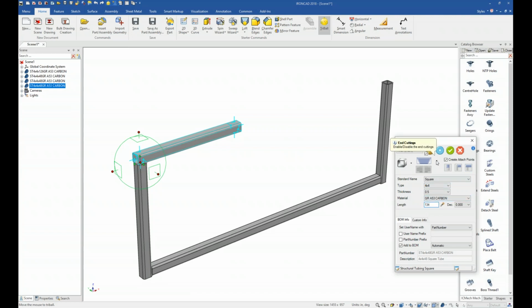And we can add some additional intelligence like the end conditions, such as the start section. We want it to be rotated about a 270-degree angle or 90-degree angle at the end. And we type in what those angle values are that we want. So our chamfer angles on our tubes, we can apply these here. That's what I'm typing in these values for. If we hit apply, we'll see everything adjust and fit, and we can see that our angles are the right direction.